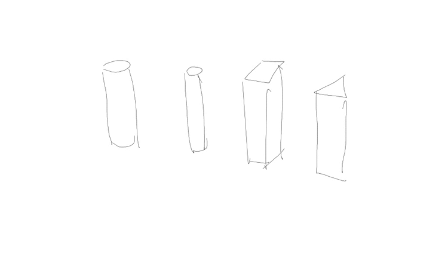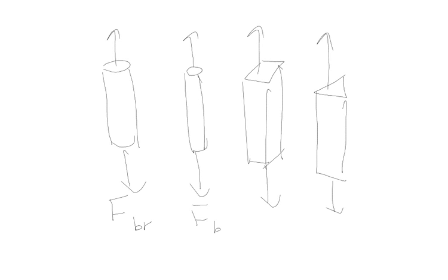Okay? And then all I'm going to do is somehow pull on each one of these until it breaks. I probably grip one end and then just keep pulling on the other end until it breaks. And then I note down the force at which it breaks, F break, let's call it. And then what I do is I take every single one of those breaking forces.